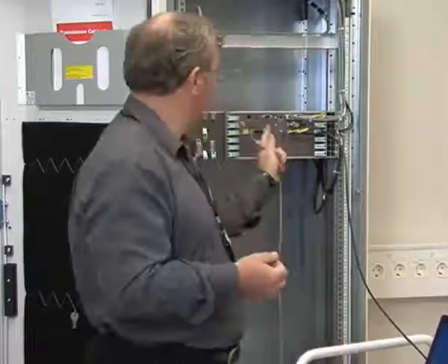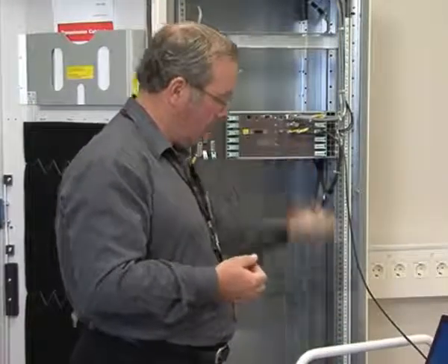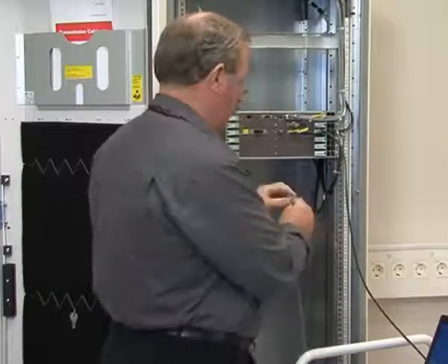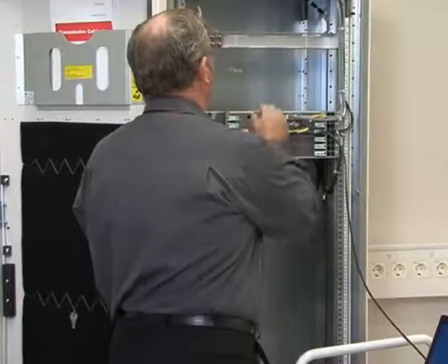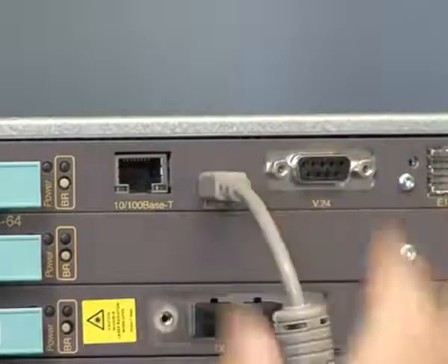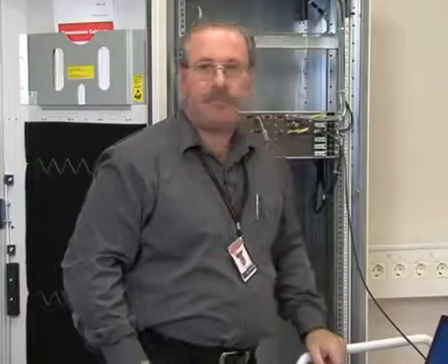Connect the USB cable between the node processor and the computer. Ensure that the USB local area network driver is installed on the computer. Refer to the Minilink Traffic Node Operation Manual if you need more information. Switch on the external power supply.